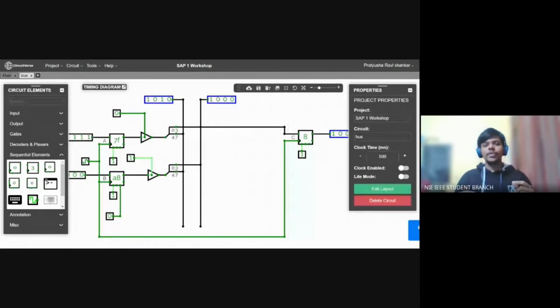Let's say you have a logic gate and you have a 0 in the input. When you look at it at a very deep low level, like the transistor level, 0 means current is flowing into that pin. So you have an IC and there's a 0 at that pin, it means current is flowing into it. If it's a 1, it means current is flowing out of it. Simple as that. The reason we need this high impedance Z state is that current doesn't flow at all. It's completely disconnected. That is the meaning of the high impedance state.